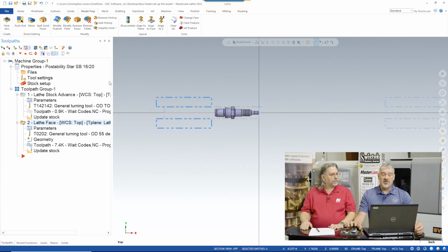And it's kind of a lot of extra clicks to go in and do this every time. So what Vince is going to show is how to set up a default Swiss operation for Poco, where you can do your Swiss machine and your CNC lathe with two totally different cutoff operations. And it's fairly simple to do too.